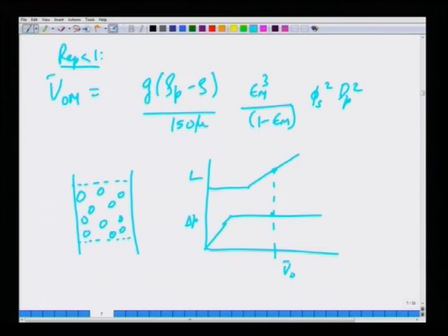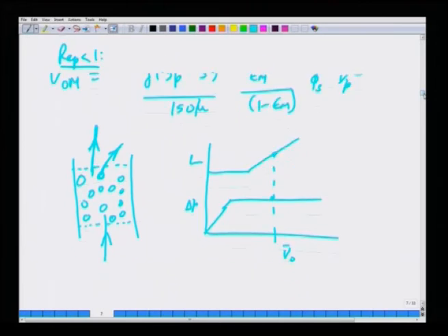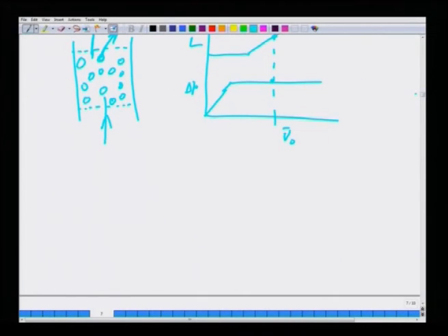The question you want to ask is whether the fluidization velocity in this regime is such that it can, because during fluidization gas is continuously coming in and going out. While the gas is going out, we should take enough care that it does not entrain particles along with it, because the whole point of our fluidized bed is to keep the particles inside the bed in an animated state of motion